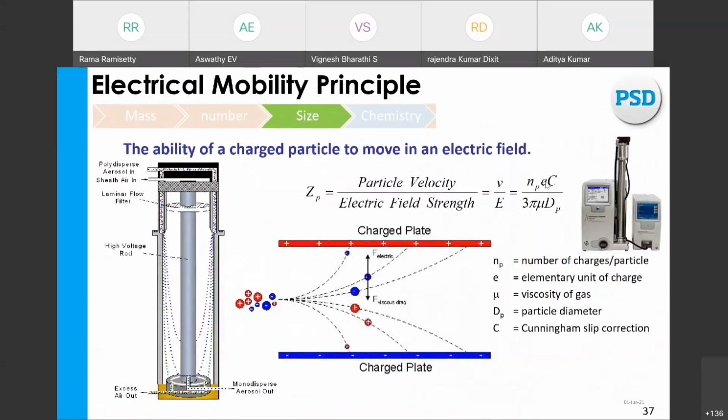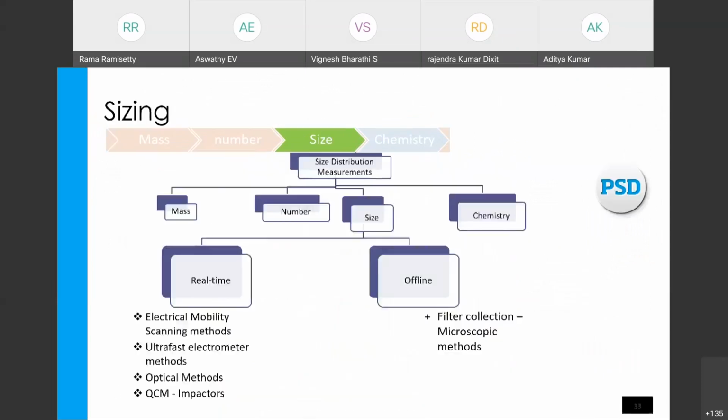For example, in the Indian context, the relative humidity is always more than 50%. For proper measurements, it should be 30 to 40%. Whenever there is a high relative humidity, there will be overestimation of the PM values. That is happening in most of the pollution control boards or most of the places. But it is not the problem of the pollution control boards. It's a problem of what we are using and how we are taking the data. But based on that data, we can get the information of how polluted each and every place is.